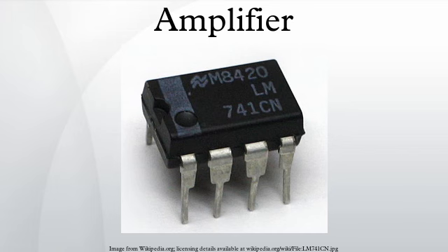In practice, the power gain of an amplifier will depend on the source and load impedances used as well as the inherent voltage or current gain. While an RF amplifier may have its impedances optimized for power transfer, audio and instrumentation amplifiers are normally designed with their input and output impedances optimized for least loading and highest signal integrity.